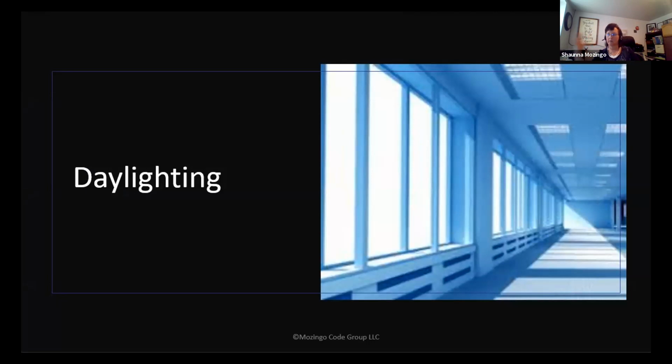But for our side-lit daylight zone next to a window, we now have a primary daylight zone and a secondary daylight zone, so we're getting further in. We're going to look at that in a minute. Some other changes: there are clarifications that lights in the primary side-lit daylight zone have to be controlled independently of those in the secondary daylight zone.